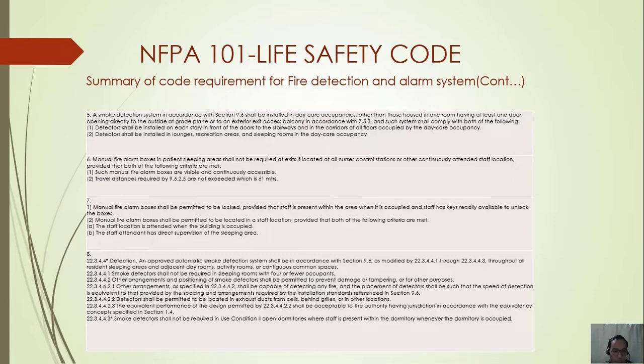detention. Smoke detector shall not be required in sleeping rooms. So if you have, let's say, jail room or sleeping rooms with only 4 or fewer occupants, then smoke detector is not required there anymore. Other arrangement and positioning of smoke detector shall be permitted to prevent damage or tampering or for other purposes.